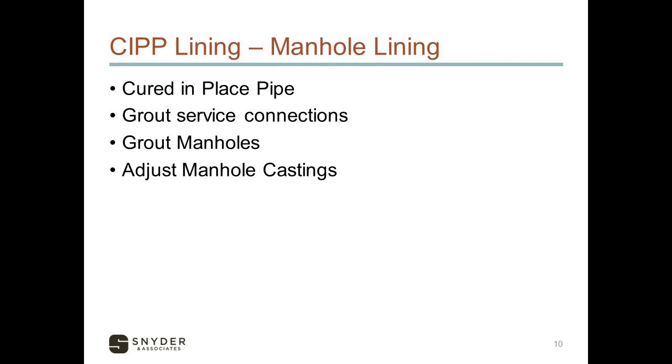We can also look at grouting your manholes, either on the exterior in the soil, or if you have the old style red brick manholes, we can do a spray-on grout concrete layer on the inside of those brick to help prevent water from coming into those systems.